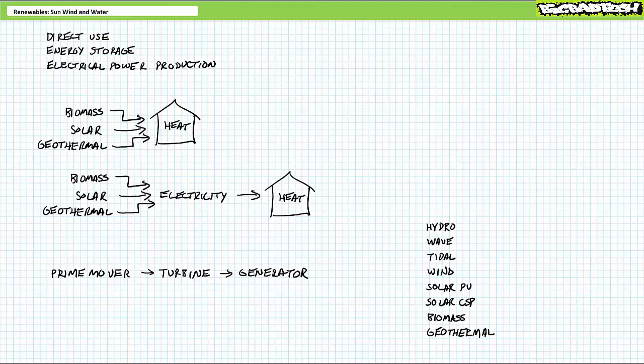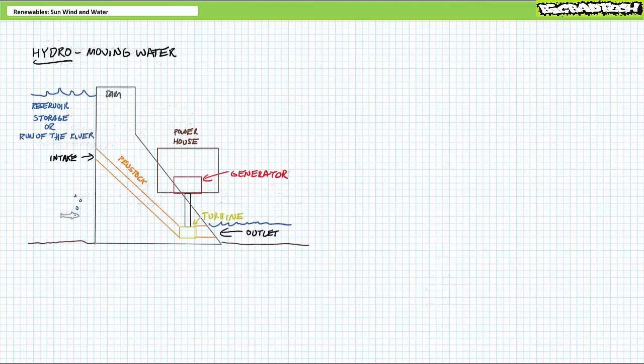Let us begin. Hydro. Hydropower harnesses the force of moving water to generate electricity. Hydropower is a renewable resource because it depends upon the water cycle, which replenishes our rivers from the snow and rain every year. Typical hydropower facilities include a dam that backs up the water to help control the river's flow. The reservoirs behind a dam are generally of one of two types, storage or run-of-the-river. As the name implies, a storage project uses a reservoir that stores a sufficient capacity of water for use when electricity demand is high, whereas a run-of-the-river project operates with minimal or no water storage.